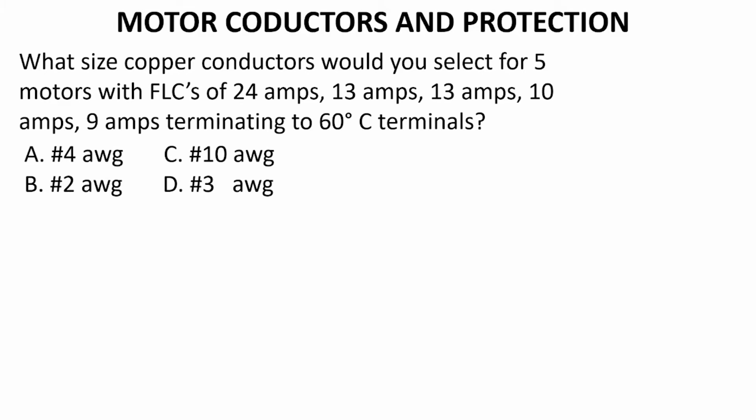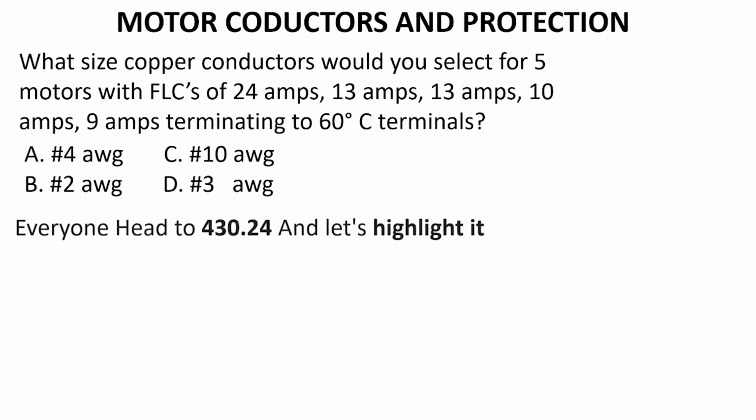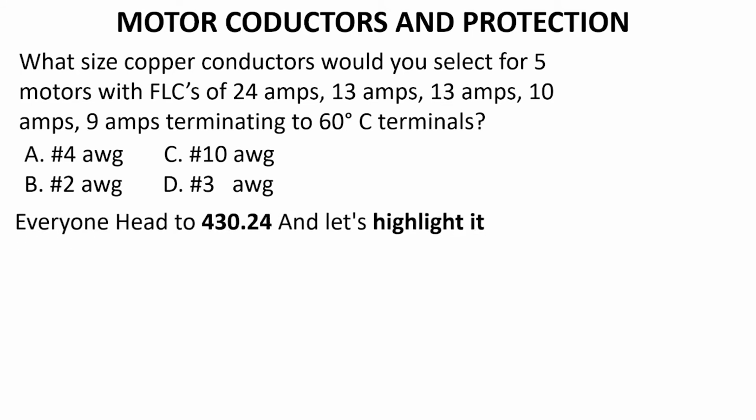What size copper conductors would you select for 5 motors with FLCs of 24 amps, 13 amps, 13 amps, 10 amps, and 9 amps, terminating to 60 degree C terminals? Everyone head to 430.24 and let's highlight it, and let's go ahead and read it.